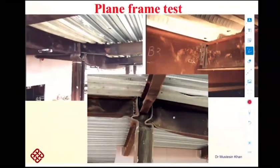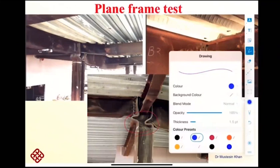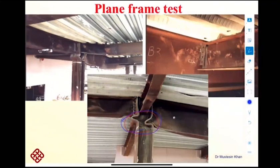And they observed that this kind of crushing happened in the column. When they analyzed what the reason for this crushing in the column was, they found out that they did not provide the fire protection to the whole length of the column. They did apply it up to this length, and above this length there was no protection, and it was directly exposed to the fire.